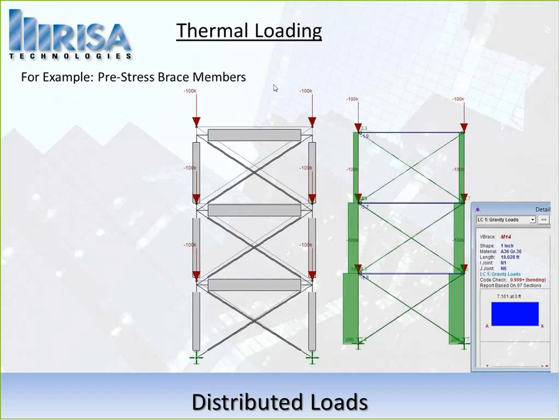So we want to examine how much axial force we need to apply so that it starts out at a pre-stress level just for gravity loads, so that it's not going to be pulled out of the model. So we see here 7.14 kips is what's happening in this lower axial brace. That's as much tension as we're experiencing right now, just from these compressive 100 kips at each floor level. So that's what we're seeing in that brace. What we want to do is get enough tension in there to overcome that 7.1. So let's say 7.5 kips is what we're going to pre-tension these braces for.